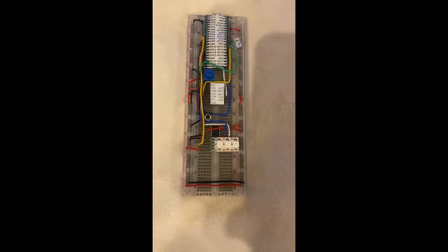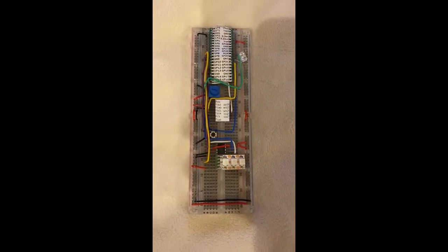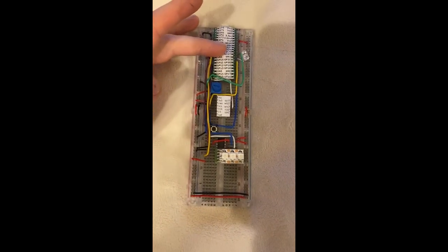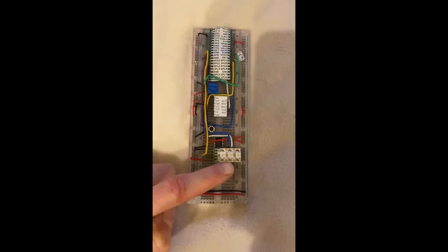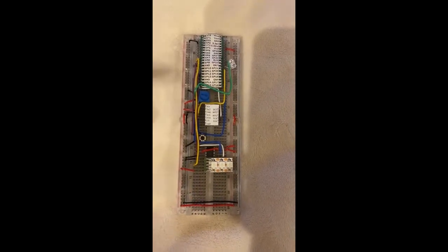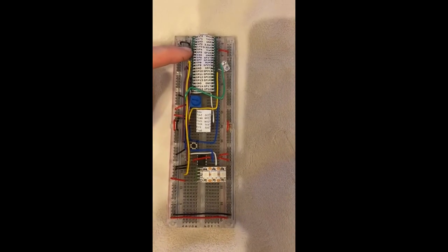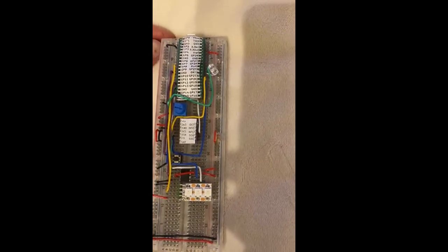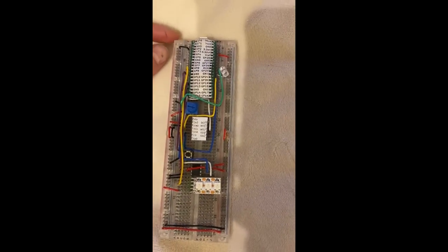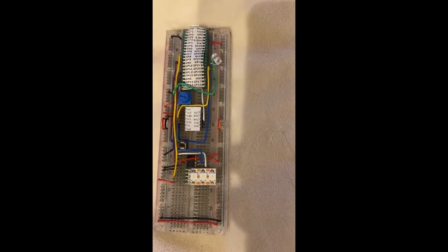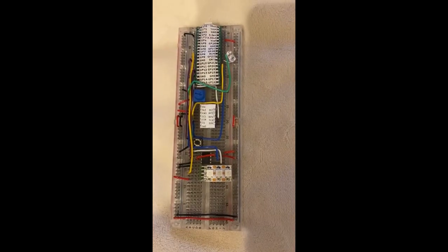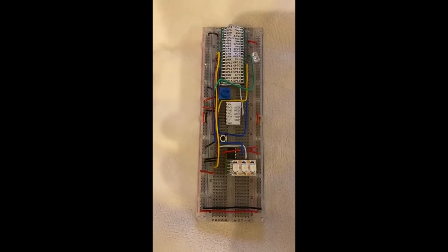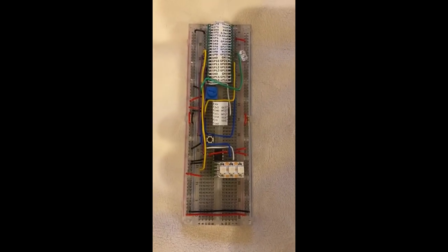I'm just going to quickly run through the three main components on our breadboard. These are the Raspberry Pi Pico board, the accelerometer, and then the RGB down the bottom. So first up, the Raspberry Pi Pico. It's the microcontroller that runs the entire project. It's small but a very powerful chip. I'm using it to process the sensor data coming from the accelerometer and control the output to the RGB. It connects to the breadboard using pins in the base, and it's been programmed using Python.